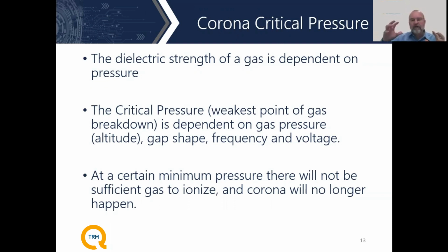As you go up in altitude, it becomes less and less, and there is a point where the voltage breakdown will hit a minimum. As you continue to decrease the gas pressure, all of a sudden there aren't enough molecules to ionize, and the standoff voltage begins to go back up again. So depending on the frequency and the voltage you have, there is a lull in the curve that you have to be careful of.